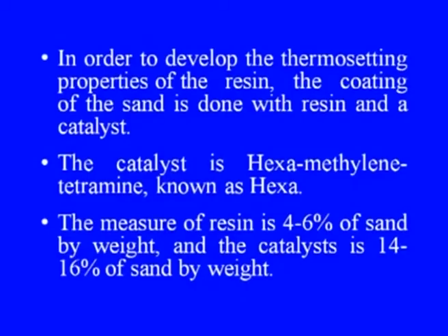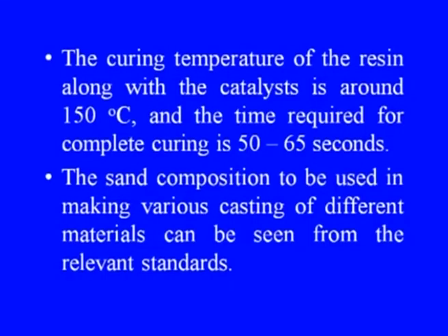The catalyst is hexamethylene tetramine, also known as hexa in short. The measure of resin is 4 to 6% of the sand by weight, and the catalyst is 14 to 16% of the resin by weight. The curing temperature of the resin along with the catalyst is around 150 degrees Celsius, and the time required for complete curing is nearly 50 to 65 seconds.